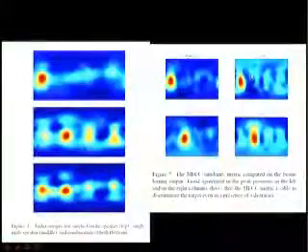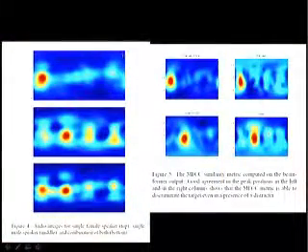So the idea of the algorithm is we beamform not only to the source, but also to the locations of the peak of the similarity metric. And now we are going to do delay and sum beamforming, but for the beamformed signals from the spherical array output.